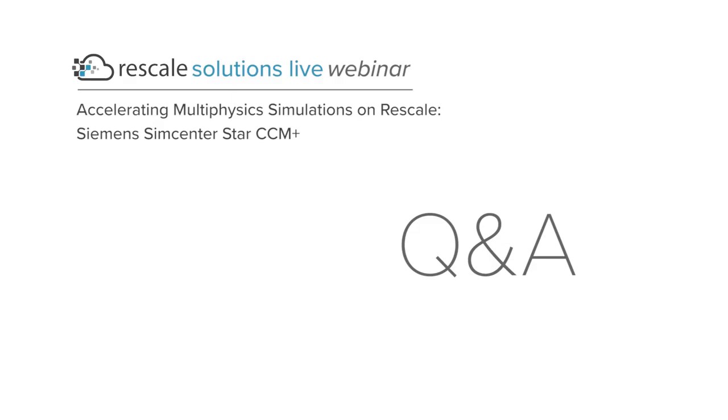And let me add something. That's why we generally recommend to stop your single design simulation not based, for instance, on the number of iterations, like 500 iterations each, because what can happen is that one design totally converged with the 500, whilst another design was really not converged at all.